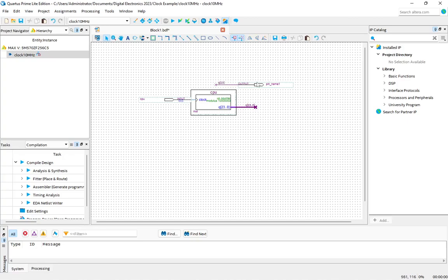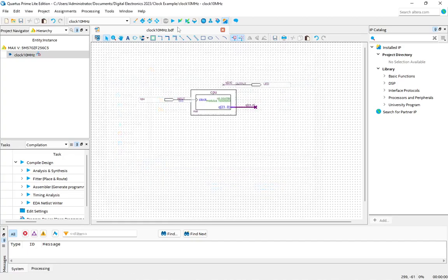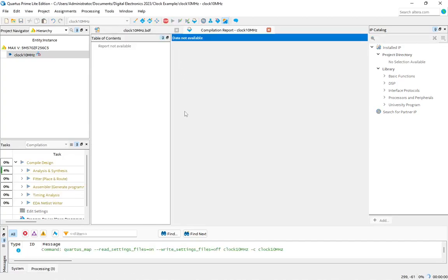That selects the highest line, which is what we are going to use to get the 1 second. And then, as usual, you have to name your outputs. Especially for this lab, you have to name your outputs. That is not an option. So you have to always make sure that you label your outputs. So after that, just save that, and then build.